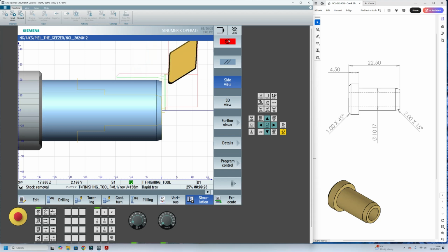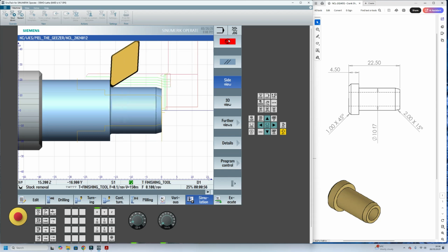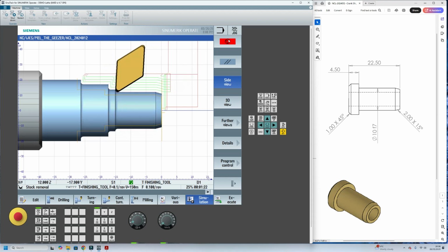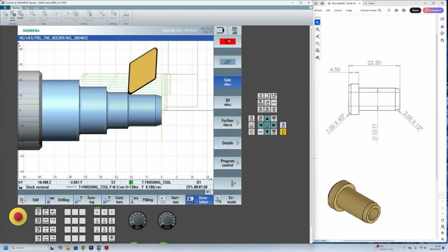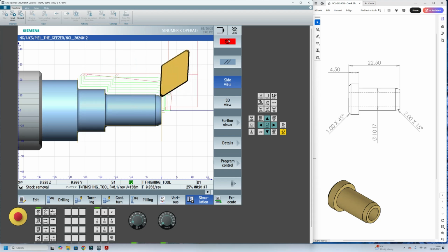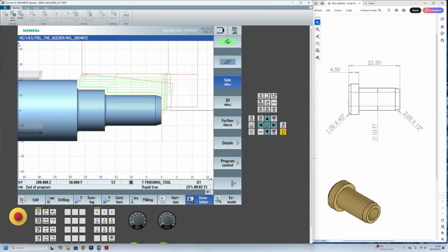So that first cut missed. I could safely go to 20mm bar if I wanted to, but I'm just going to leave it as it is for clearance. It doesn't hurt. Now, if we were running 50,000 of these, I would be wiping that out to make sure I'm actually cutting on the first pass. Right, the outside contour is what I'm going to call it, or the outside profile. It doesn't matter, but away we go.